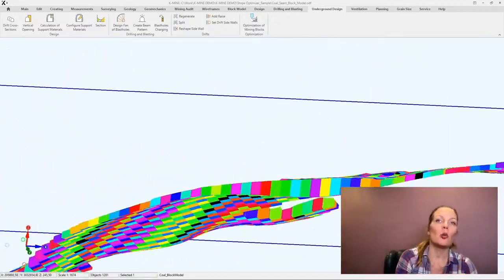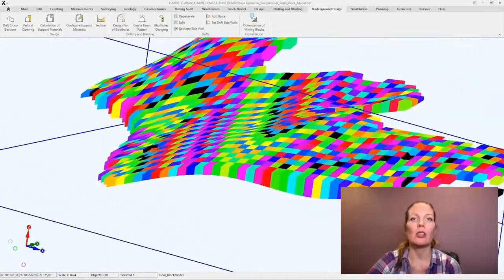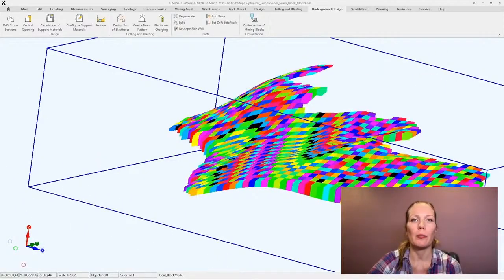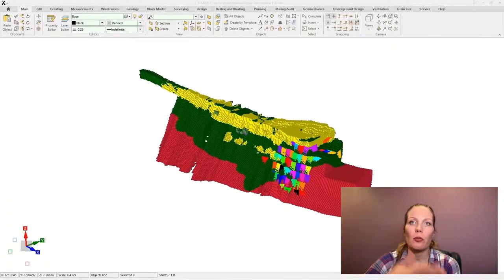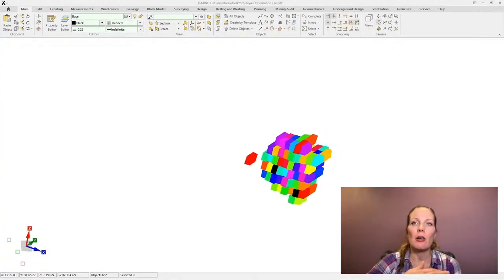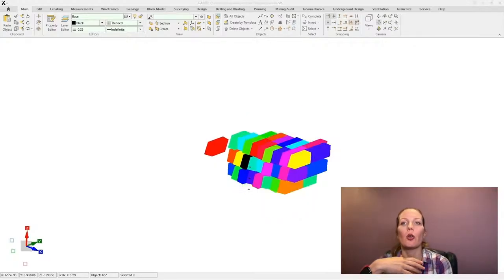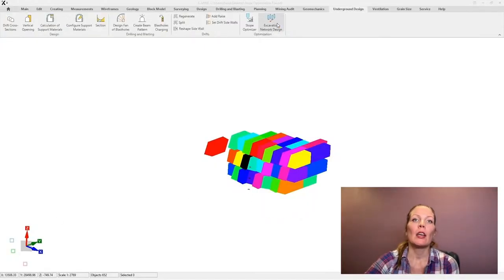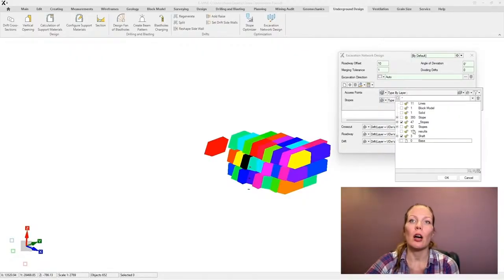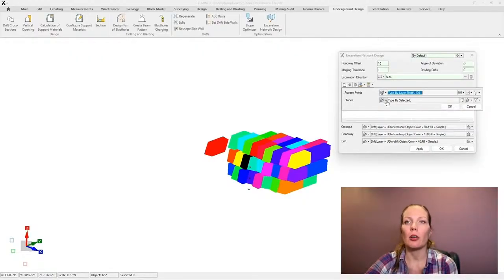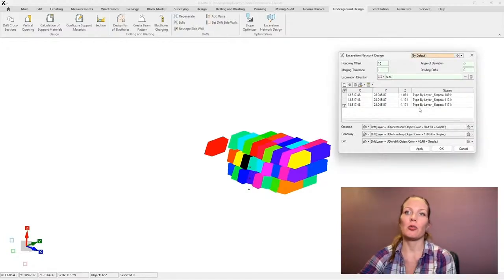So the stopes that move forward are workable, economically justified, and correctly oriented with respect to the ore body. K-Mine's stope optimizer does most of the hard work up front. It starts directly from the block model, grouping blocks into clusters that follow the ore body's strike and dip, keeping each cluster within the angle limits allowed by the mining method, evaluating economics, and, most importantly, preserving the geometry required by the chosen method.